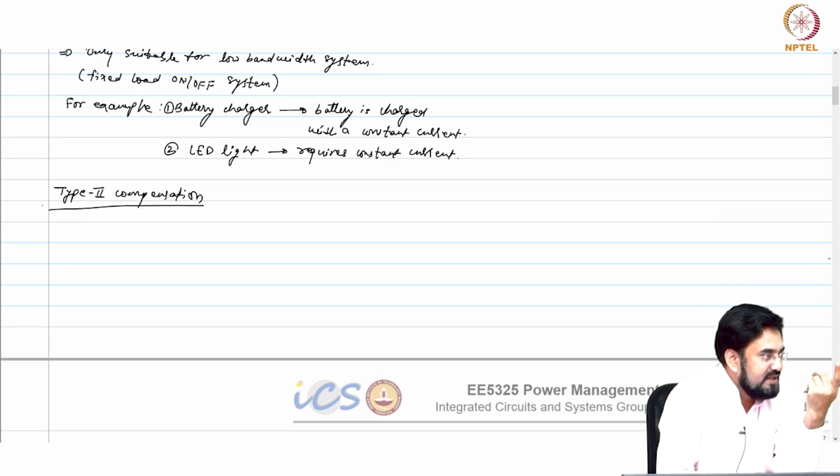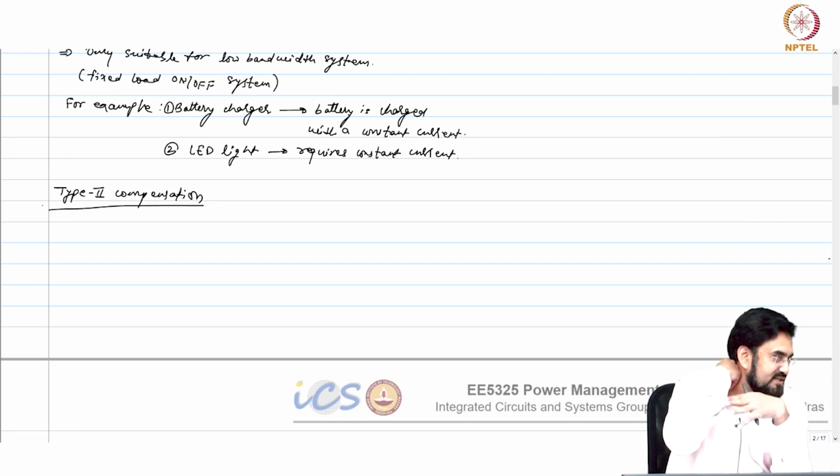So, in the type 2 PLL you have 2 integrators, one is coming from your VCO, the other is coming from your charge pump. Okay, VCO you require, so by default that is introducing one, because that is your clock generator, and charge pump you require with the loop filter in order to close your loop, because you have to convert those phases into voltage.